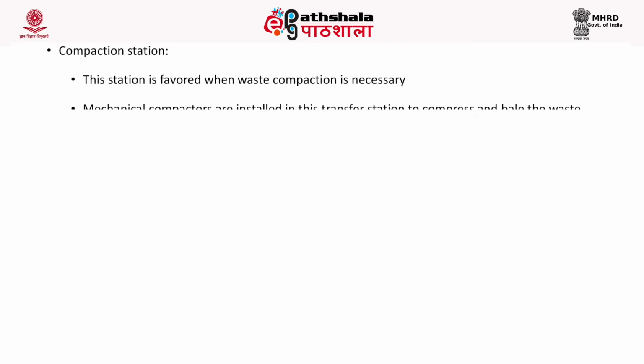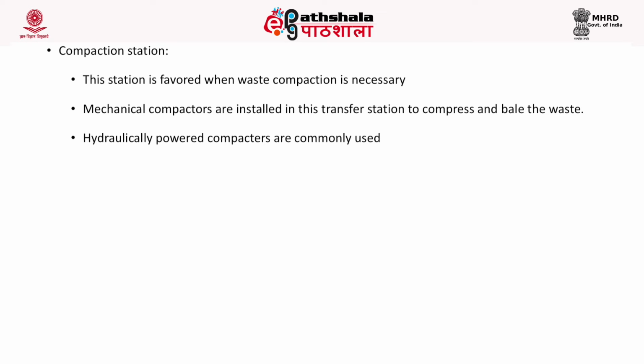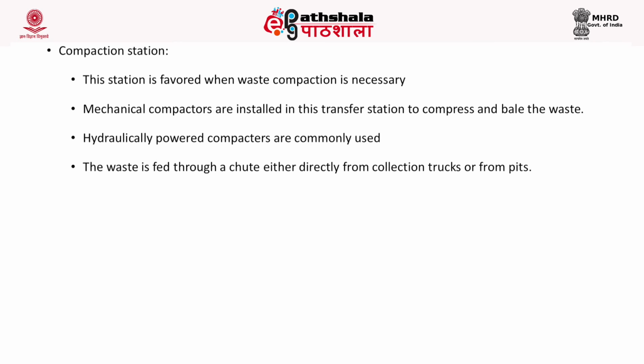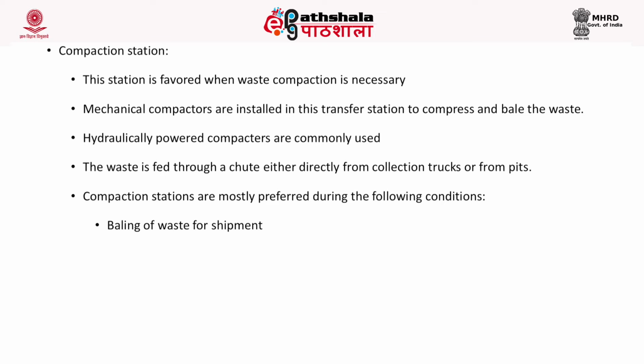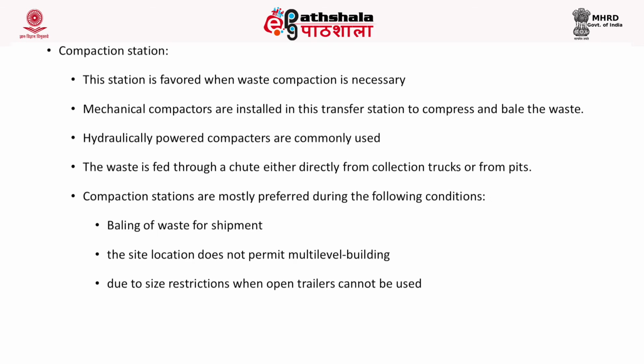The third type, the compaction station. This station is favored when the waste is to be compacted. Mechanical compactors are installed in this station to compress and bale the waste. Hydraulically powered compactors are commonly used for compacting the waste. The waste is initially fed through a chute either directly from the collection trucks or from pits.